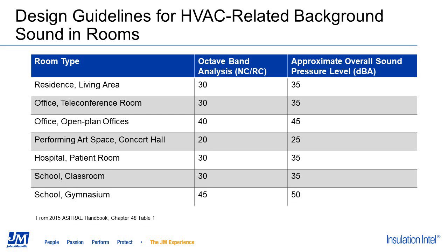So I picked a few spaces that I have taken from a table from the ASHRAE handbook. This is chapter 48. This is the typical standard for developing acoustic models of ductwork, as well as prescribing proper vibration isolation for various mechanical equipment. This shows a couple of spaces that I pulled from that table, with their recommended NC and RC ratings. Acoustic consultants would use a table like this for guidelines for analyzing a space for a system design to see what treatments or equipment may be needed.